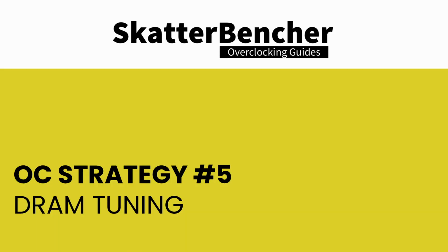In the fifth overclocking strategy, I have a look at the memory subsystem to see if it has any impact on system performance. The memory subsystem obviously consists of the memory controller and the system memory, and then the system memory consists of its frequency and the memory timings. To tune the memory subsystem, I use the ASUS memory presets from the Z890 Apex from the board here behind me, and also some manual timing adjustments.